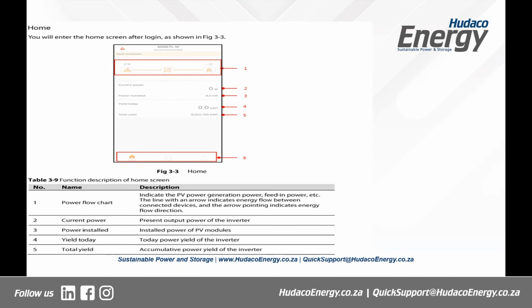That is the power made up of your PV modules. That is where you see it. And then the yield of the day is number 4. You see how much you have produced today. And then the total yield is the amount of power that has been produced over the period since the inverter started operating. And at the bottom of the screen, you still have your home, your faults, and me.